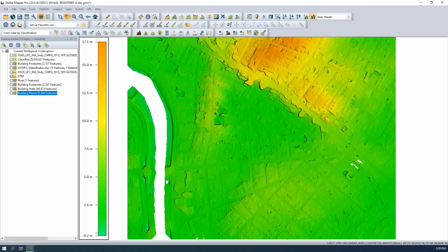We also have a large sort of slash through this data set here. Now this area is a river. This is the Charles River. And I have an area feature, a polygon representing that region. So to edit this terrain grid a little bit, maybe fill in the gap, this river, as well as some smaller holes here, I'm going to start by just selecting my area feature, and we'll see why in just a minute. And next I'll open the terrain painting tool.